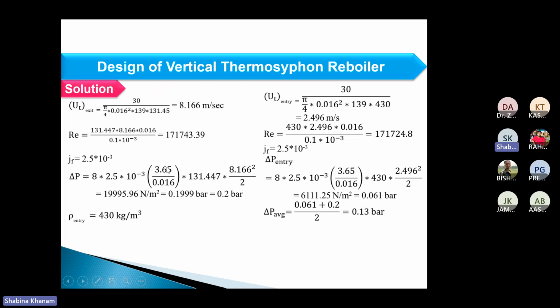And if you see here, I have considered total length, because when we talk about pressure drop in tube side, we always use the total length. You also have to consider this in shell and tube heat exchanger, either Bell's method, Kern's method, whatever.